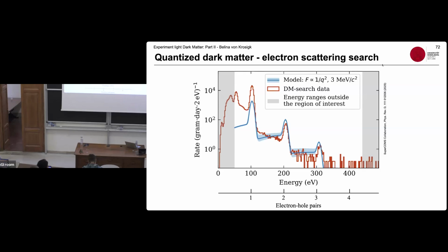And then coming back to the question we had earlier, I told you already that you will find fill-ins between the peaks, and this is from the impact ionization that I mentioned already. So you have the electron being released and being propagated and kicking out another electron that is now also being amplified, but partway through, so it's only getting a partial amplification. So a 1 electron hole pair can in the end look like something like 1.5 electron hole pairs.